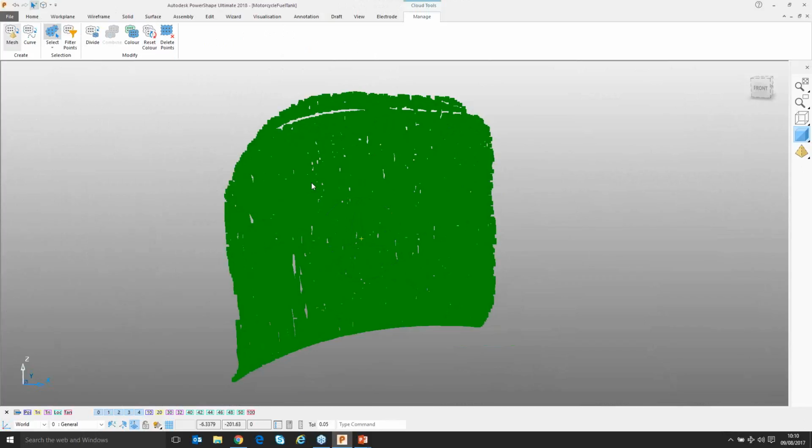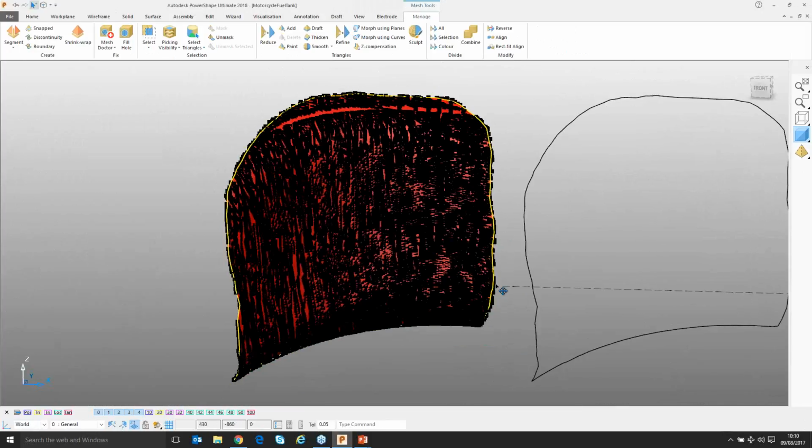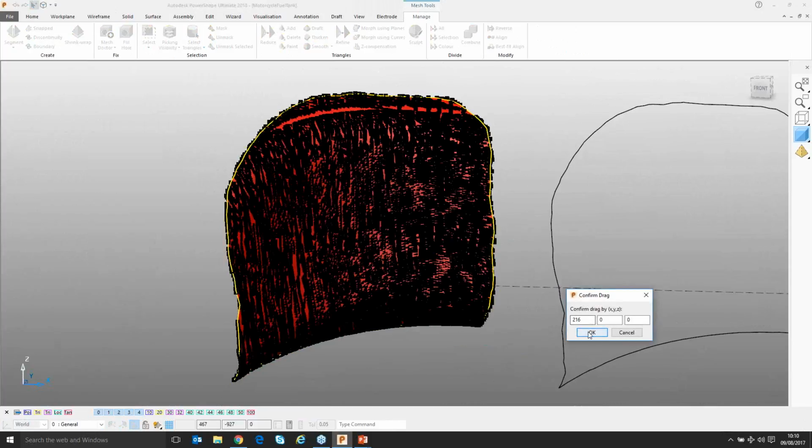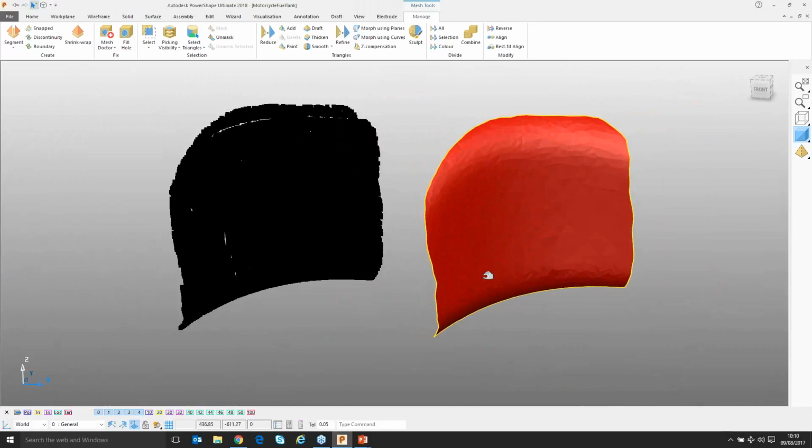So once I've done that, I'd like to go and create my mesh. If I leave the whole diameter at the defaults that have been suggested here and hit OK, we're going to get a result over this. Let's take a look what we get. I'll take the mesh and drag it out to the side here so we can see a mesh there, some faceting going on there.